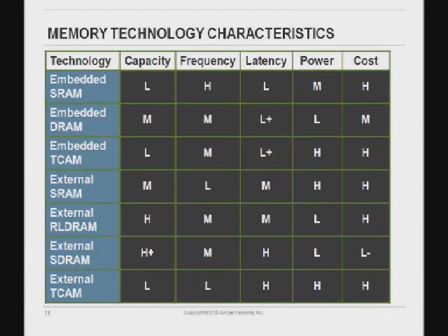There's also another one I highlighted here, the TCAMs. Those are the ternary content addressable memories. With normal memory, you give in an address, you read out the data. The TCAMs are exactly the opposite of that. You give them the content, and they come back with which entry matches that content. So TCAM has been used in networking for a long time. It's very valuable to do ACLs and the like, and even lookup.